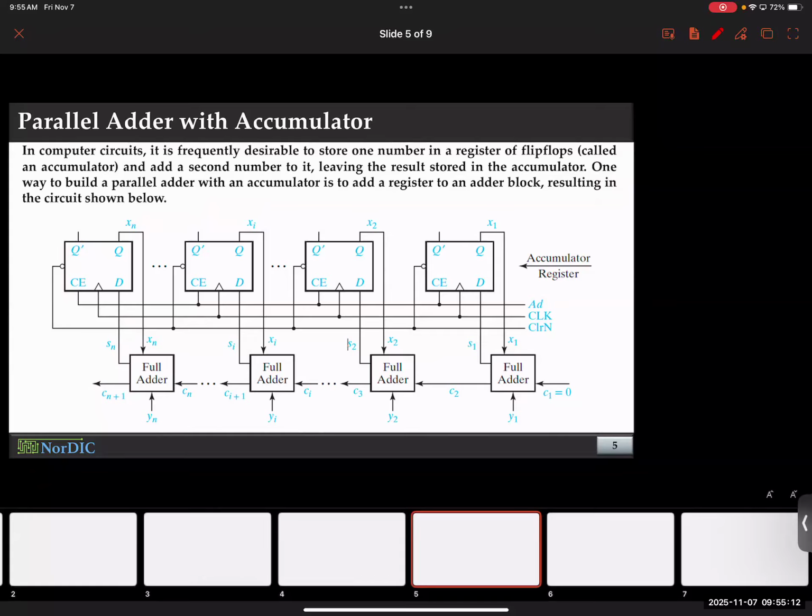So here we go. We have a full adder. We have an adder chain. Typically, we just have the carry out going from one level to the other and done. And we provide X and Y as input. But that is not really usable in a situation where you have multiple numbers needed to be added, right? How can you add like 5 binary numbers? You cannot. You just add 2 numbers with an adder block. So there has to be a way, and this is an easy way.